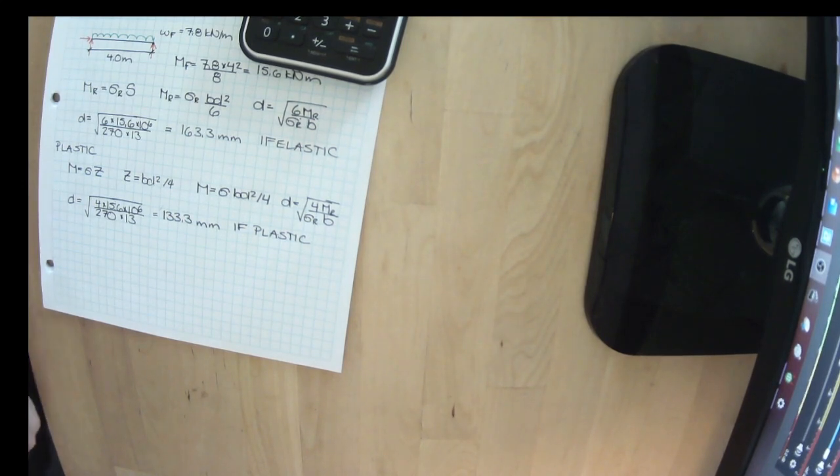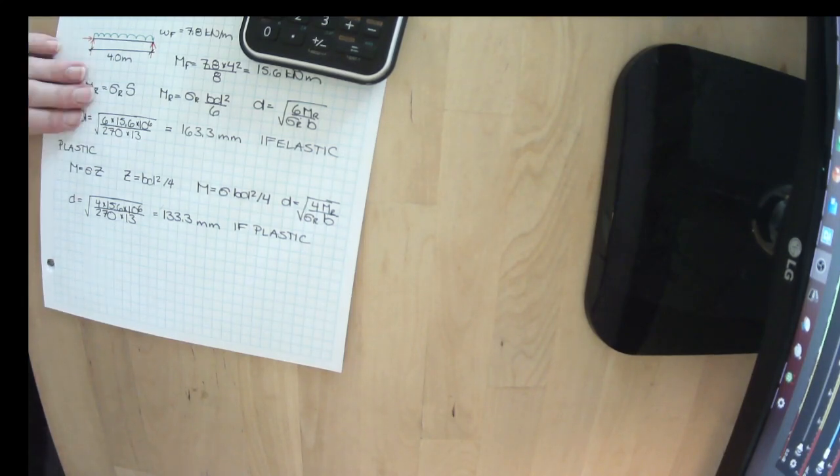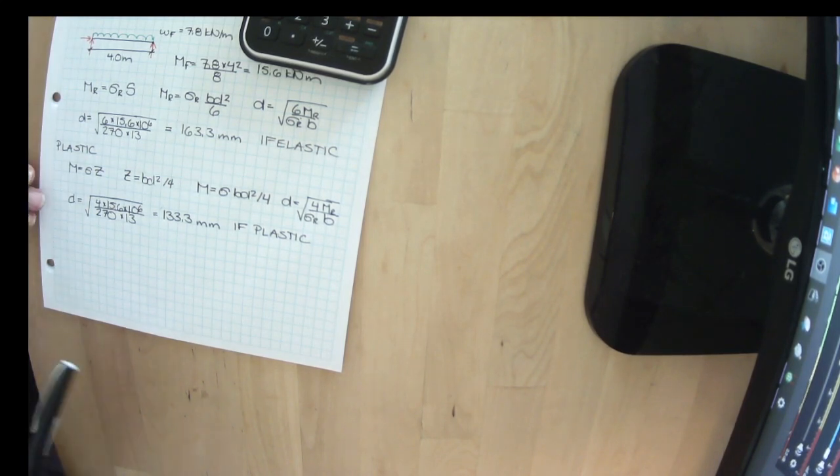So we have to know when we can use plastic and when we can't. Well, first off, if it's a brittle material, we can never, ever, ever use plastic. It would fail. There is no plastic zone. This is the only thing that would work, because when we hit the end of that linear elastic zone in our stress-strain diagram, our material fails.